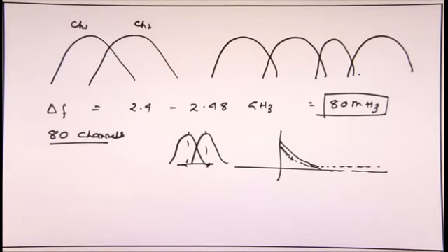Yes or no? So you understand that I need a kilohertz level of resolution in a gigahertz channel when my channel is crowded with say 80 such channels. That means my channel spacing is restricted to 1 megahertz, and then I need that kind of resolution.